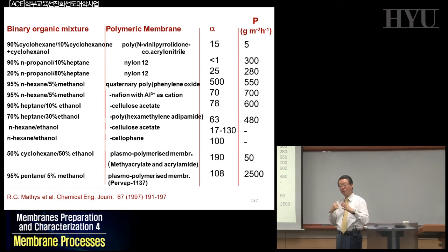Okay? So if you have a pervaporation process of this aqueous ethanol, 90% ethanol solution as a feed at around 100 degrees C, the water vapor will meet this membrane, and the water vapor will be only collected in your vacuum system, and then you can condense those vapors, whereas the retentate will remain as your product, okay?